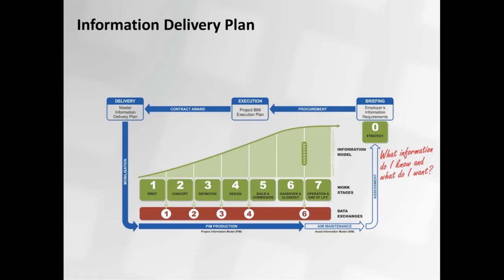I hope to be able to go very quickly through this idea once again so that it's finally cemented for everybody. This all starts from the information that the employer wants, given previous experiences of how they want to improve on the process. And then the BIM execution plan is the response of a design team to this. It is supported by an MIDP, which is a Master Information Delivery Plan, that is the sum of all those documents that we've seen, that detail who's doing what and when.